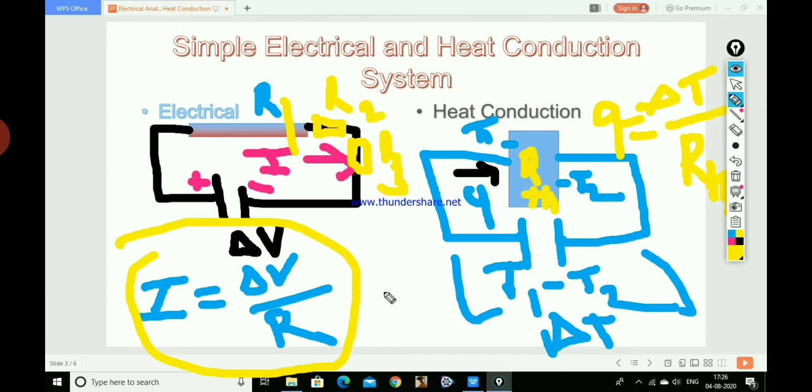Similarly, if we are having plaster as an extra layer on our wall, our slab, and another extra layer, then R thermal 1, R thermal 2, R thermal 3 are generated. As this is in series, we take R_TH1 plus R_TH2 plus R_TH3 equals R equivalent. So using this analogy, our problem becomes much simplified and we can easily solve it.